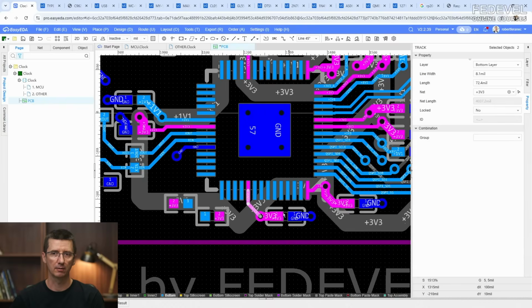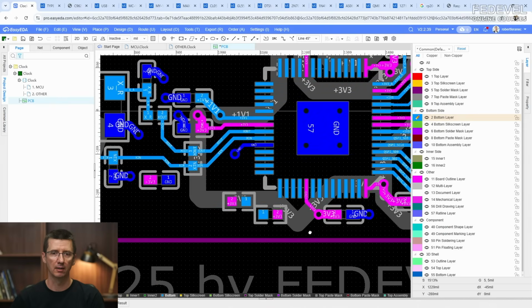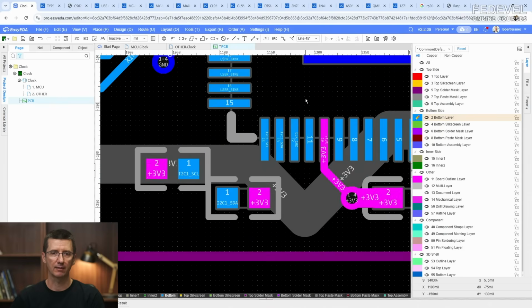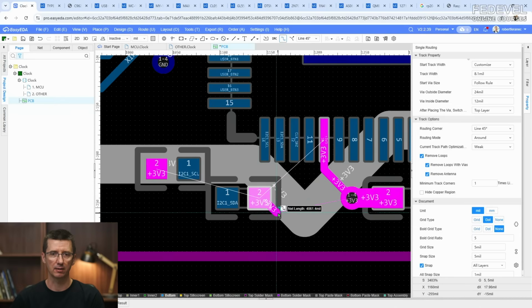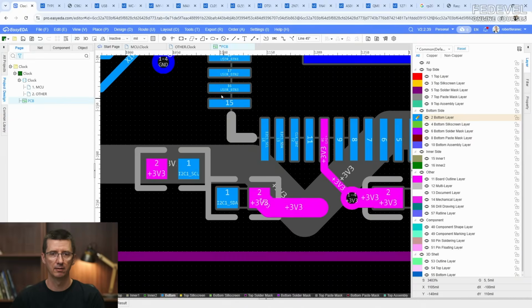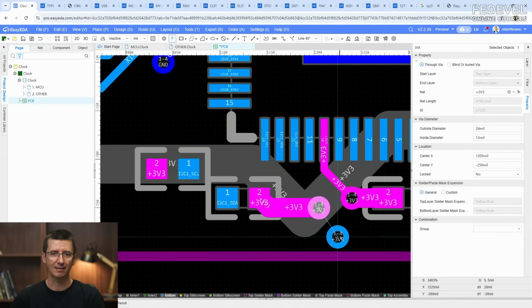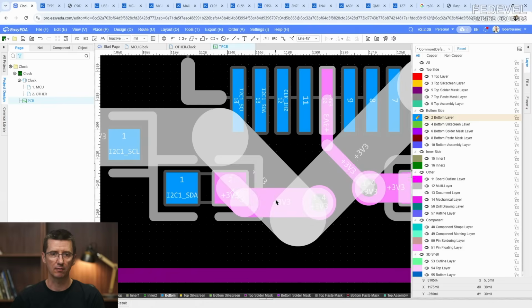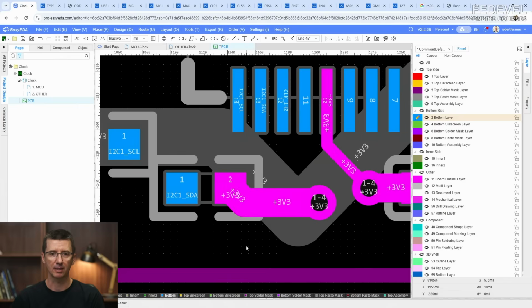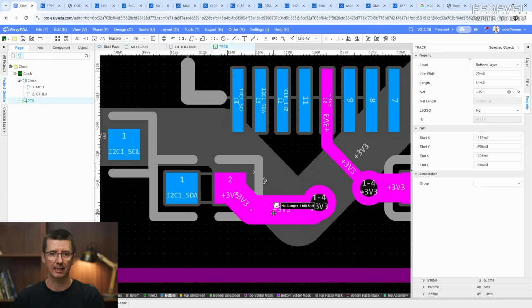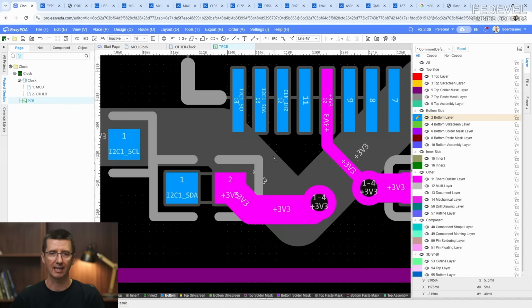Notice this, it's very important, because the path from the microcontroller is very small, so I had to use thinner tracks. But I didn't want to use 8 mils because by the end of the design we will be changing all 8 mil tracks back to 6 mils, and I don't want to change the width of power tracks. That's why I use 8.1 mil.